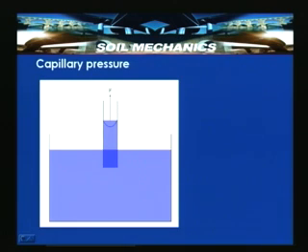That is the force with which it could pull the water column occupied in the tube against gravity. Now, these are the surface tension forces acting all around the periphery of the tube. D is the diameter of the tube, which is nothing but the pore size in soil.